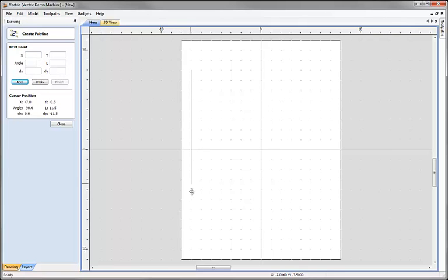So I'm going to click there, then I'm going to come down, and we're going to have a length of 18, angle of 90, so that's essentially coming down to the one almost in the corner, straight line across to the other side, and then up to the point which is level for the first part we created, which is another length 18 line. I'm going to click there.